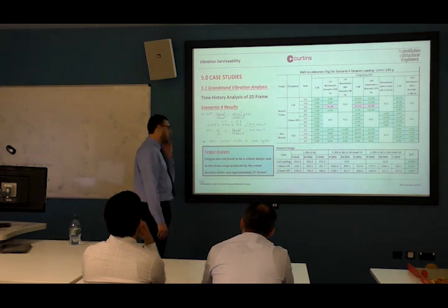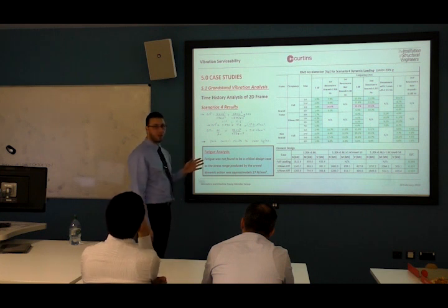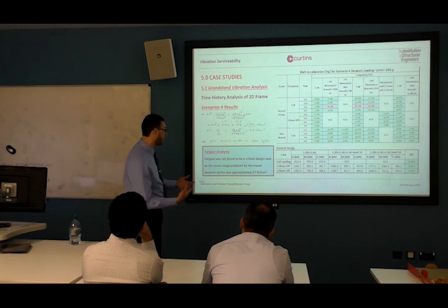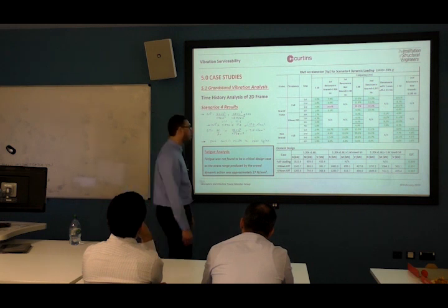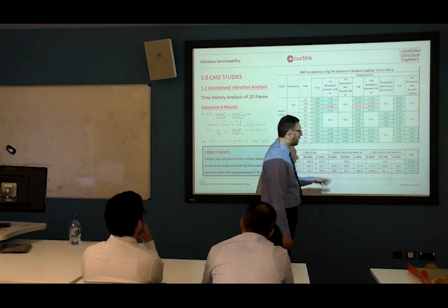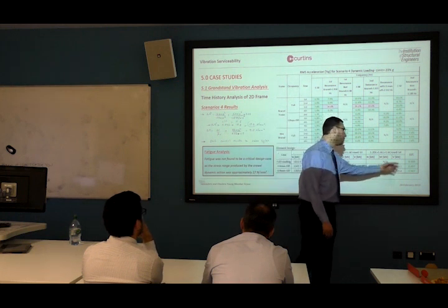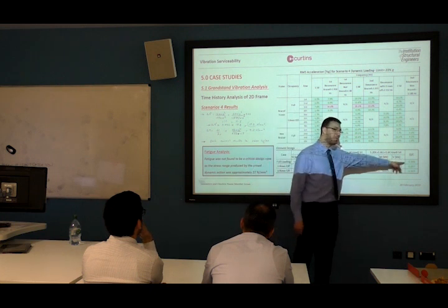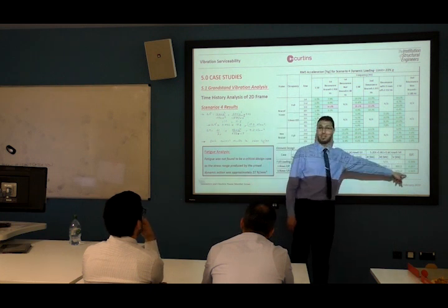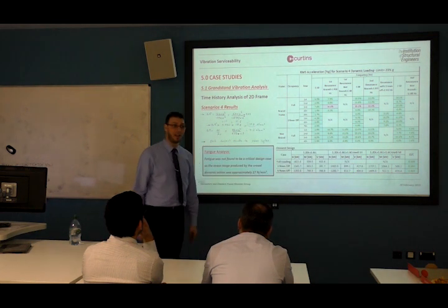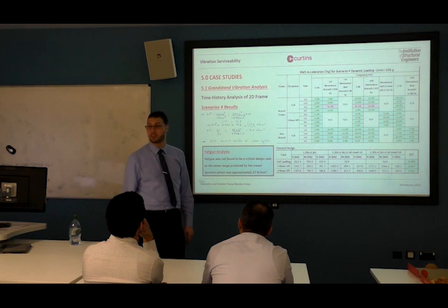And then thinking, okay, but this is scenario 4, we have to check the ultimate limit state as well for the building or for the structure. So what we had to do is to check what is the crowd action when you do the ultimate limit state analysis. And this number is a real number, 0.999 utilization ratio. And I think this is how steel manufacturers do profit actually.